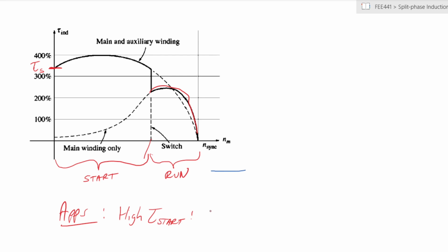And these are things like ACs, things like compressors, and certain kinds of water pumps and so on and so forth. This is equipment that needs a high torque at the start. ACs, compressors, fridges, and so on all require a high starting torque because there is inertia of the load. Such systems need to pump the liquid. So like in the case of compressors, you need to start compressing the liquid when it has inertia. And so that is the main use of these particular types of capacitors.